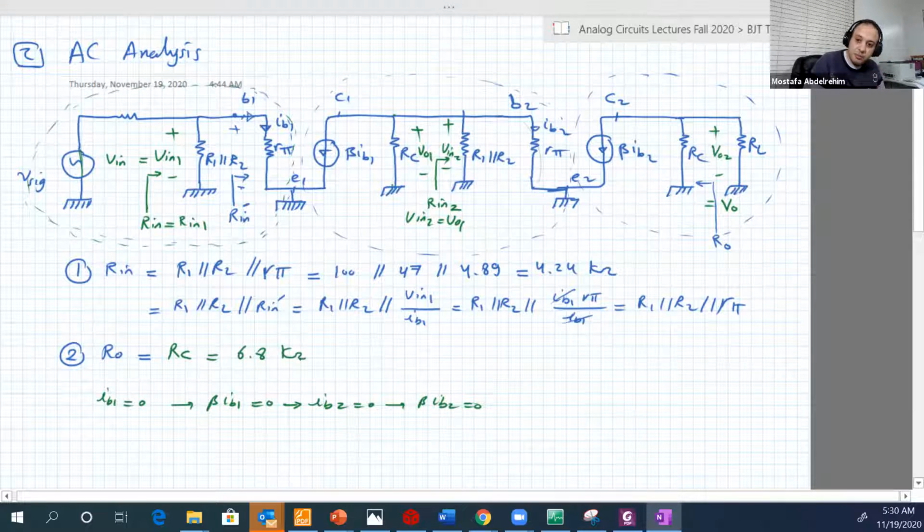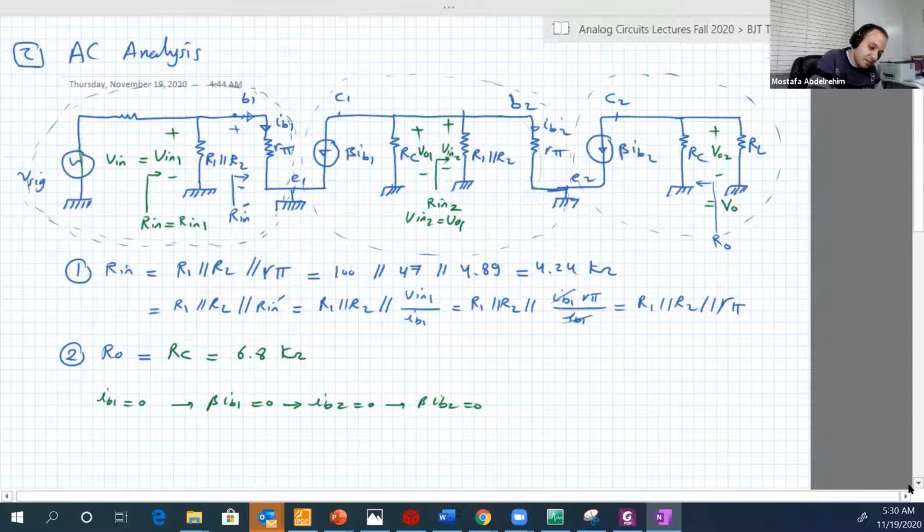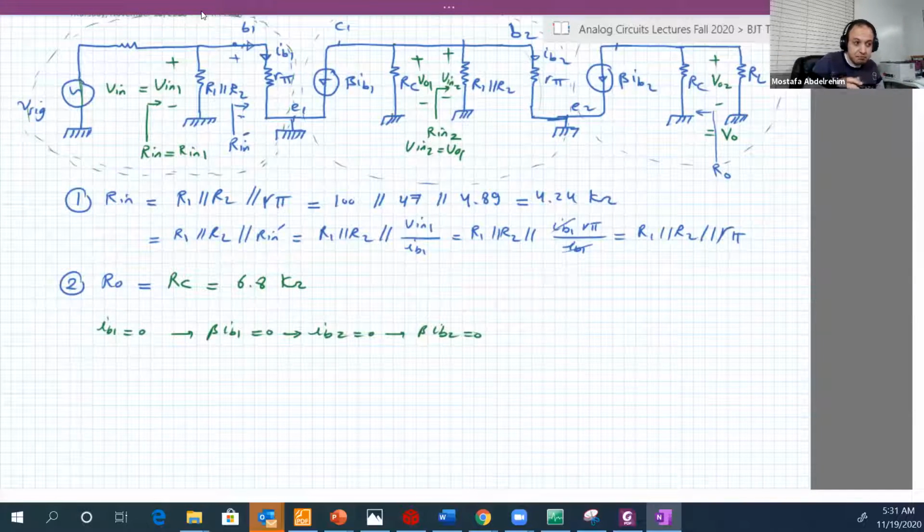It's pretty high. Look, we said that a good circuit should have low output resistance, high input resistance. If you look here, the output resistance is actually higher than the input resistance. So till this moment, we doubt where is the advantage of having 2 stages, but we will get to it now.